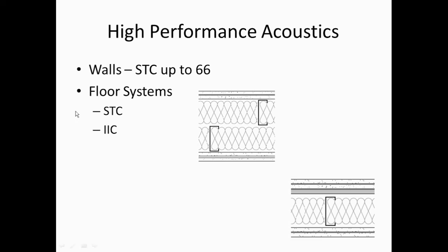To design for that, you have to follow the guidelines that come up with an IIC, impact isolation classification, and the testing for that is kind of interesting. But the point I'm trying to make is cold-formed steel framed assemblies in floors provide excellent IIC characteristics.